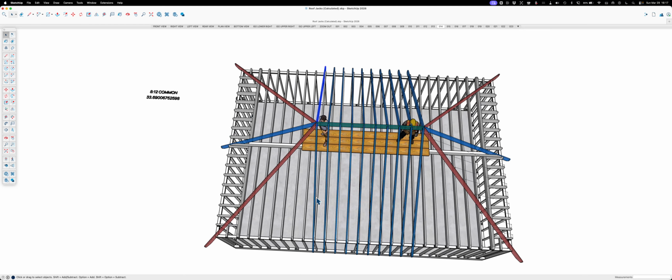You could have a cut guy in a factory, and this would take him not even a day, probably half a day, to cut all this, label it, put it on a truck, and then when you guys are ready for roof, there it is. And as soon as somebody complains, then I would check square, make sure the spans are correct. Don't let this thing creep. Be a professional.